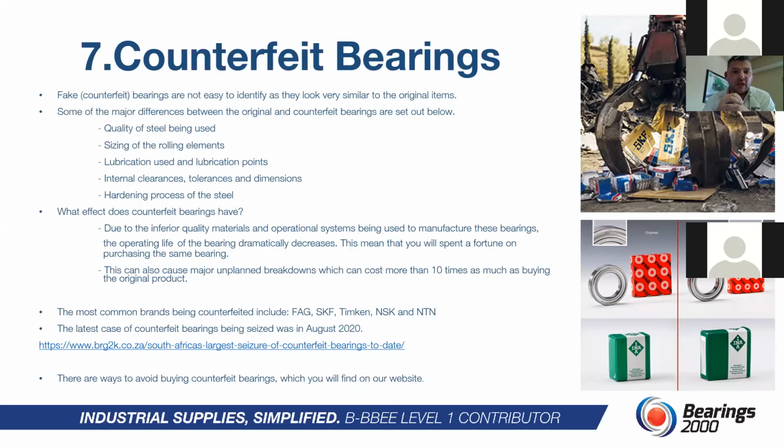But some of the major differences between the original and the counterfeit bearings are the quality of the steel used in the manufacturing process, the sizing of the rolling elements, the lubrication being used and the lubrication points of the bearings, the internal clearances, tolerances, and dimensions of those bearings, and then the hardening process of the steel.